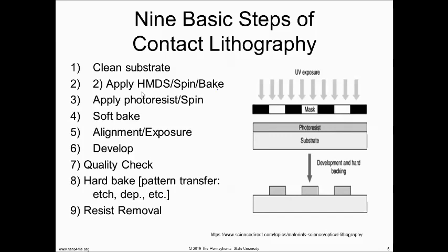So what I have to do is apply the HMDS, and what that does is remove the water vapor from my wafer. This allows my photoresist to stick. Does everybody get that? That's what I'm trying to do.